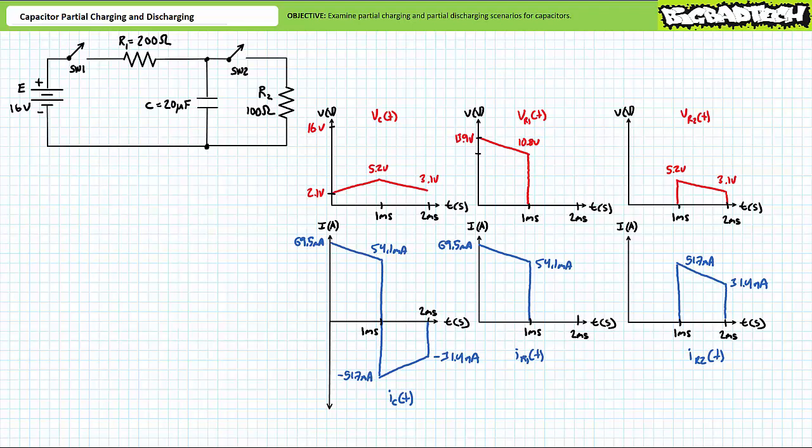Assuming we repeatedly partially charge this system through R1 for 1 millisecond, immediately followed by a 1 millisecond partial discharge through R2, we might see voltage across the capacitor continually oscillate between 6.7 volts and 4.1 volts. If you want to go out 3 decimal places, you're looking at an upper limit of approximately 6.708 volts and a lower limit of approximately 4.068 volts. And this is after like 7 or 8 cycles.